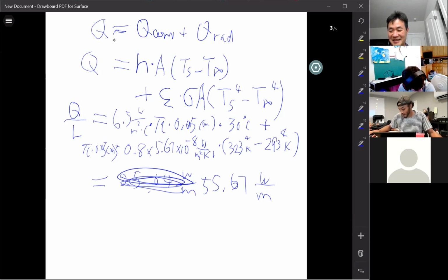I had got a value for each one. I just don't know what to do with it. You shouldn't get a value for each one. They are the same. Before you can figure out the surface temperature, you shouldn't be able to find any Q. Your difficult part is the surface temperature. You need to know the outside surface temperature when exposed to the air, which is not given for this problem.